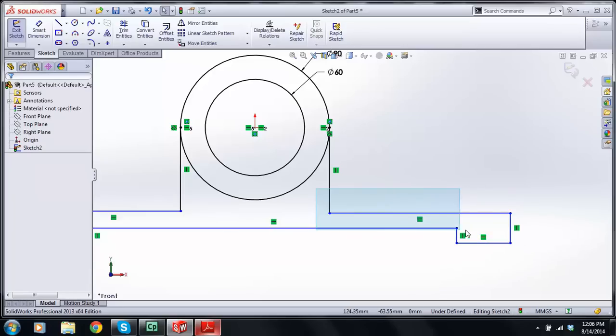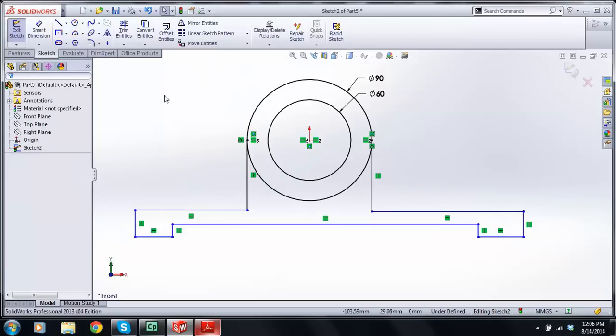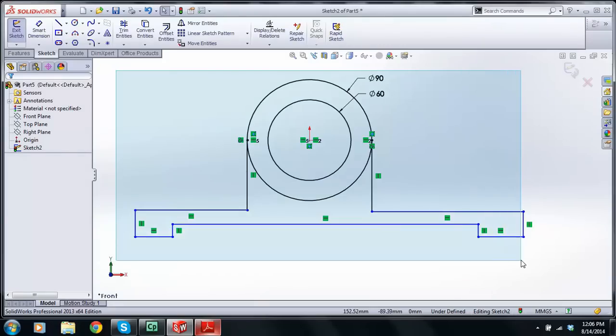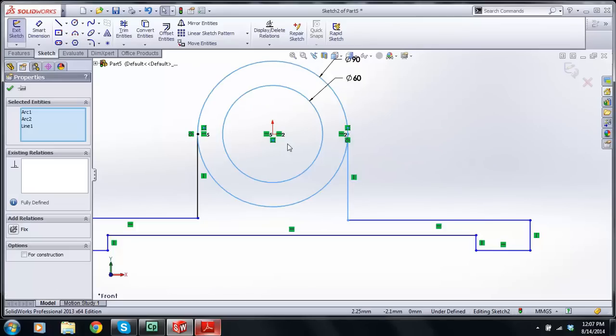What about here? What's it going to highlight? It highlights nothing. Okay, so that can be kind of useful. You can go in there and highlight certain things. Now watch this. That's going from left to right because it's blue. Now if I go from right to left, it's green. The thing with green is it'll highlight whatever touches the green box. Now what is it going to highlight in this? It's going to highlight the two circles and the vertical line, like so.